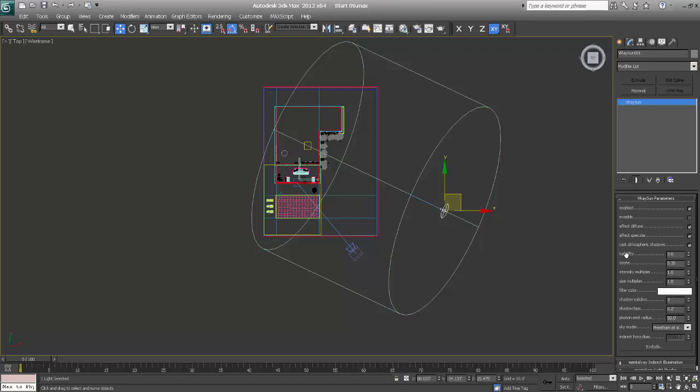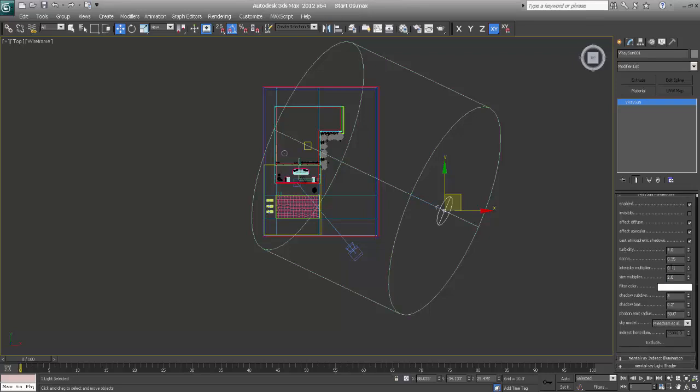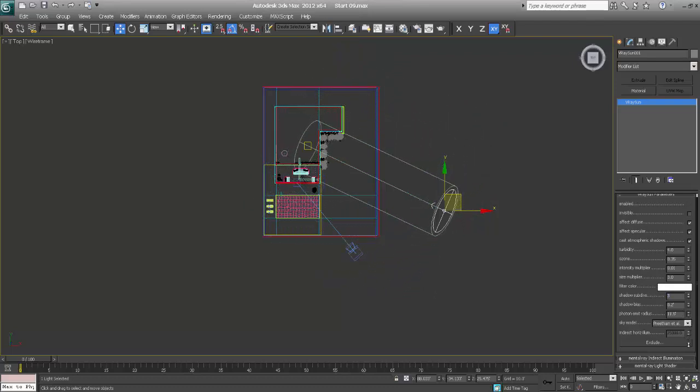So before doing a camera setup or any other setup, I like to go into Vray sun settings. So generally I start with a turbidity of 4 for the evening scenes, and multiplier I generally start with very less, 0.01, and size multiplier maybe around 3 or 2. Size multiplier basically gives very soft shadows, and if you want more soft shadows, I can increase up to 3 also. And regarding that, here is shadow subdivisions. So if your shadow is looking grainy, we can increase it to 8 or something like that. Right now for test renders 3 is fine, and we don't want to see this photon emit radius. I'll just bring this down.